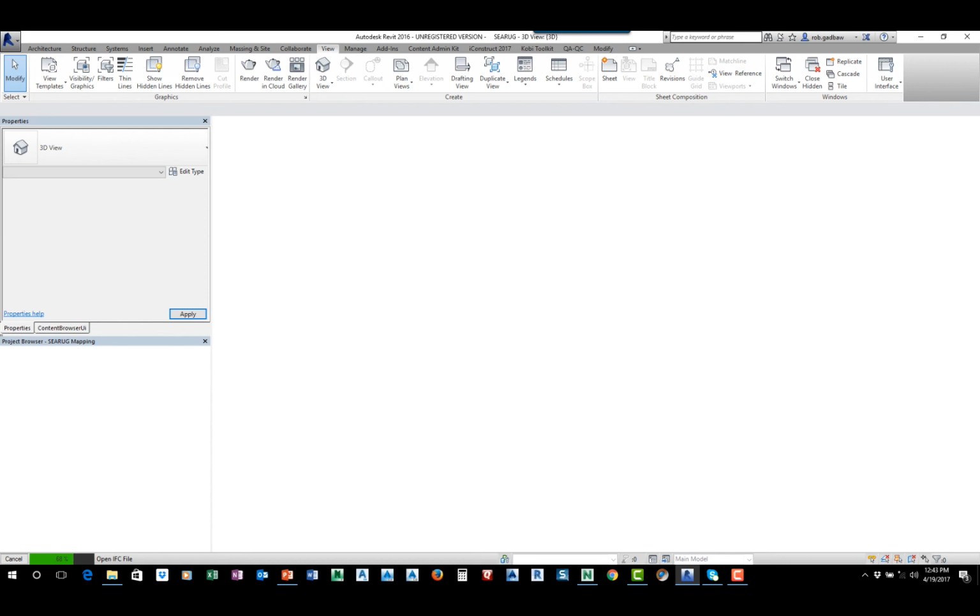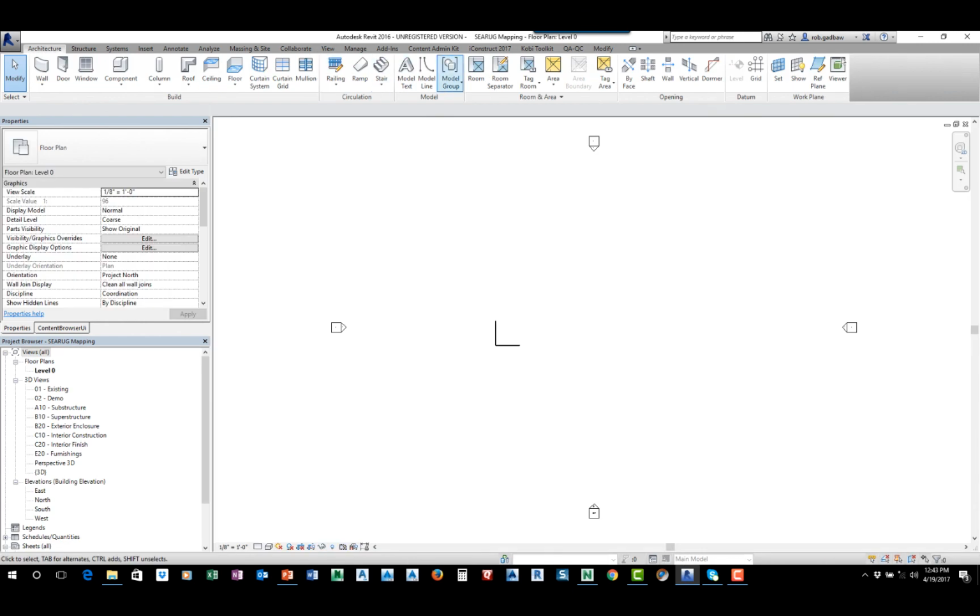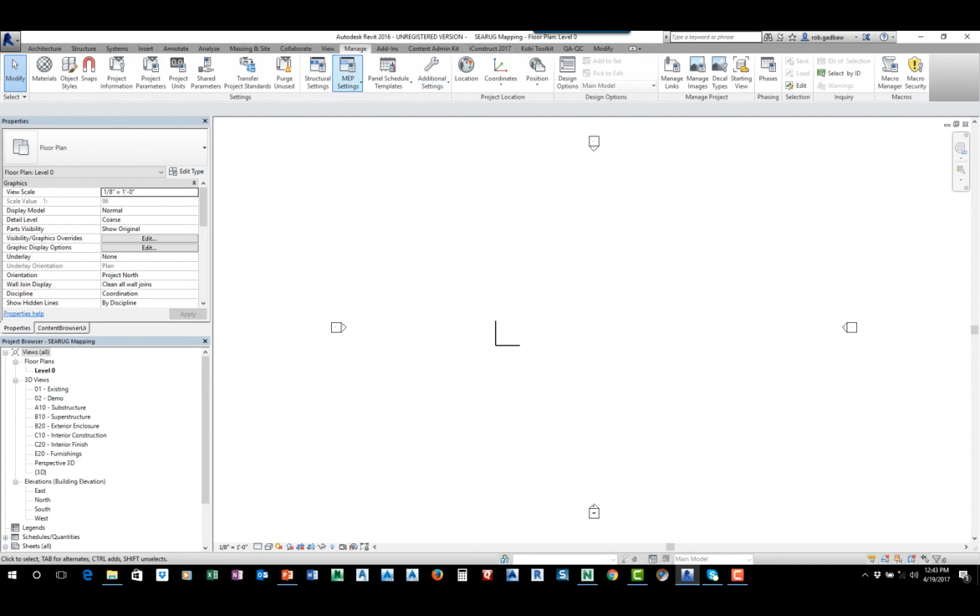Almost done. While this is doing it, some other things that we've got out or are coming also. We've got a model compare tool in here where we can compare a model from one day to the next, not only geometry but data. So you can open up two Revit models and just quickly do a check, and it'll create you selection sets of what's all been added, what's been deleted, any property that's actually changed, so we can do that.